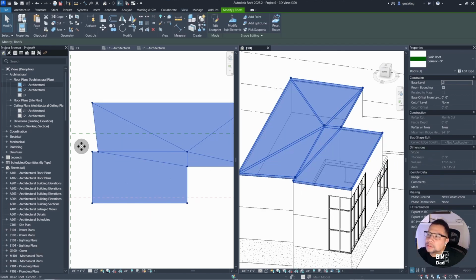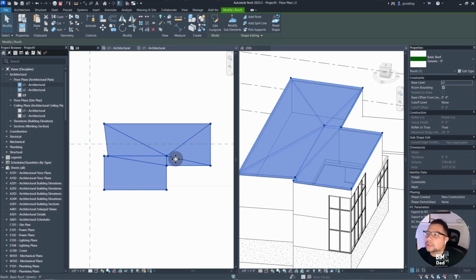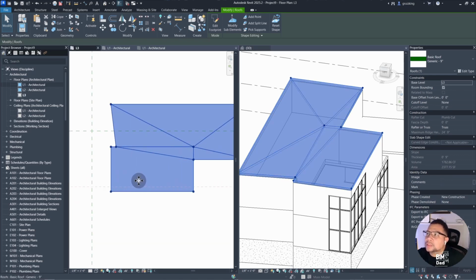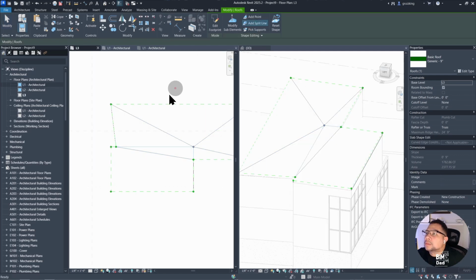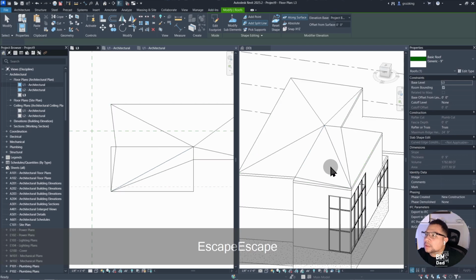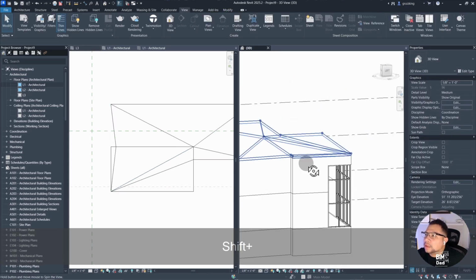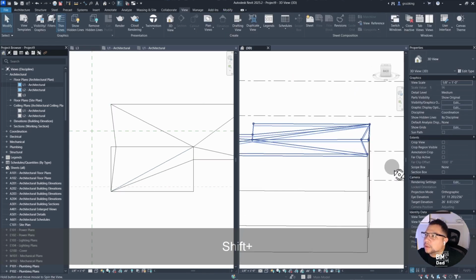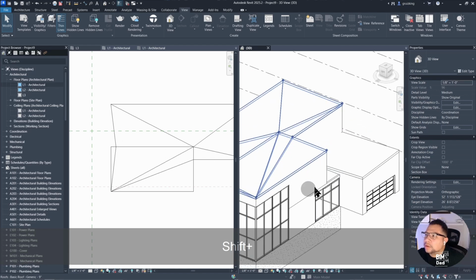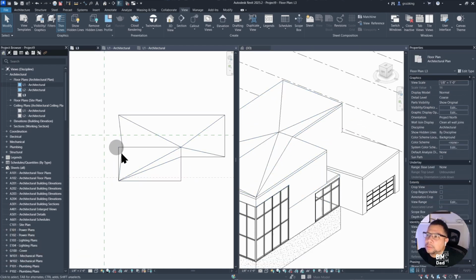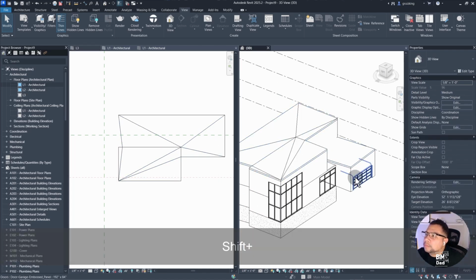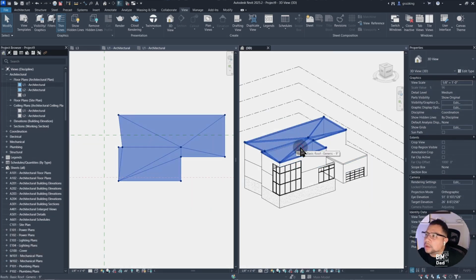Now this is something kind of weird. This would probably ideally be split into two. That's too much for one drain potentially. But let's say that we wanted to keep going with that. I could add another split line here. And you can see now that that line is meeting down at that point as well. It's creating all these weird lines that you can clean up after the fact, either graphically or by accurately breaking up the roof. But that is a basic overview of modeling the roofs.